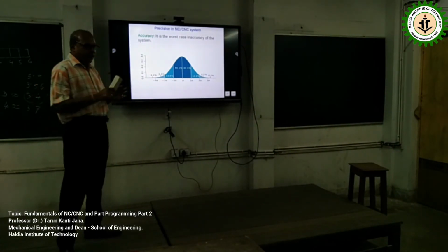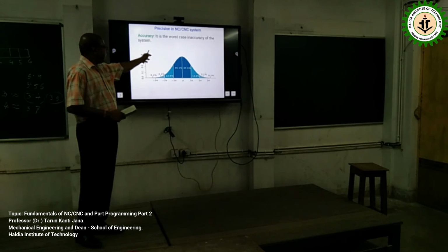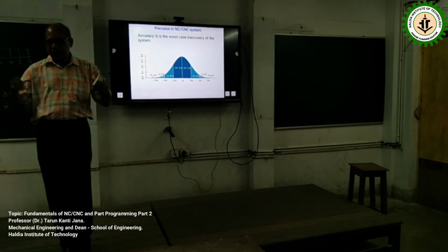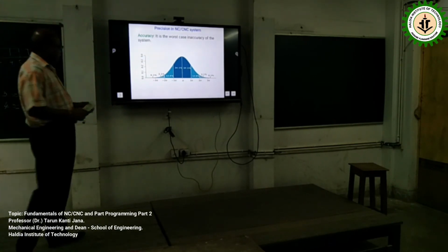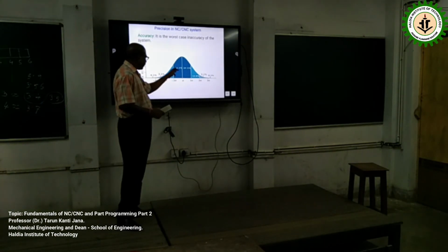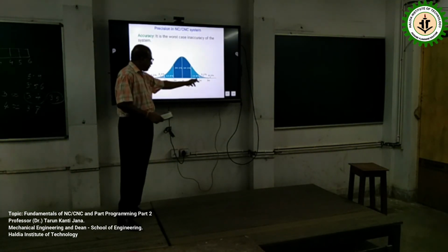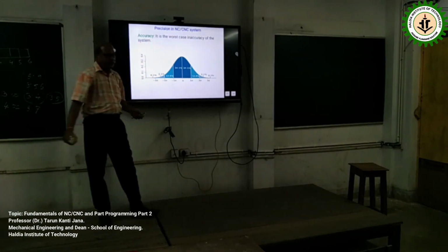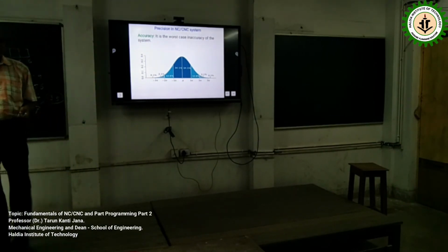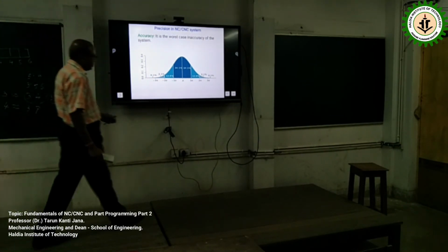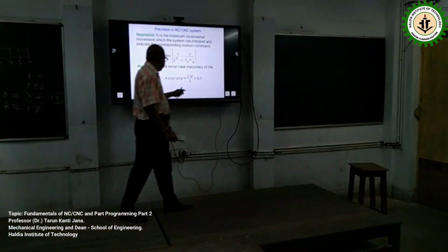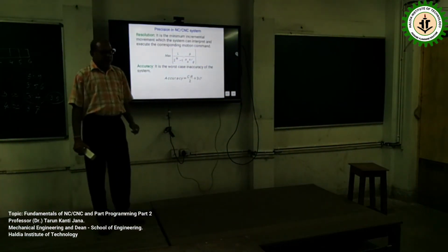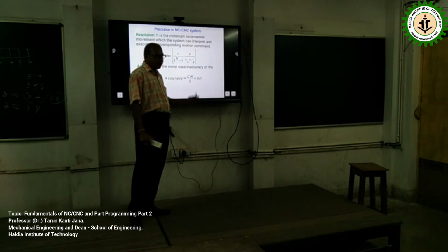Within plus minus 3 sigma limits, 99.7% of error can be captured. Within plus minus 1 sigma, 34.1 on each side, another sigma 13.6, another sigma 2.1. So almost 100% of error can be captured within plus minus 3 sigma. So that is why this 3 sigma. Now you can also understand why it is plus minus.